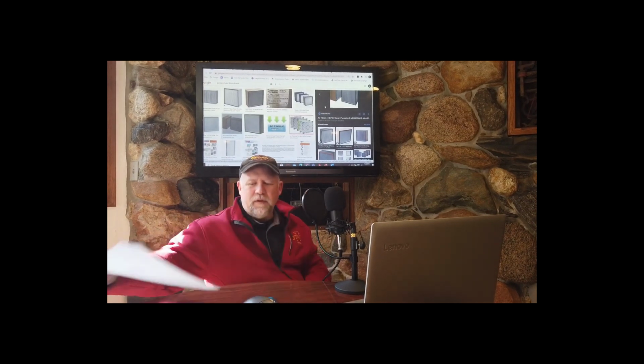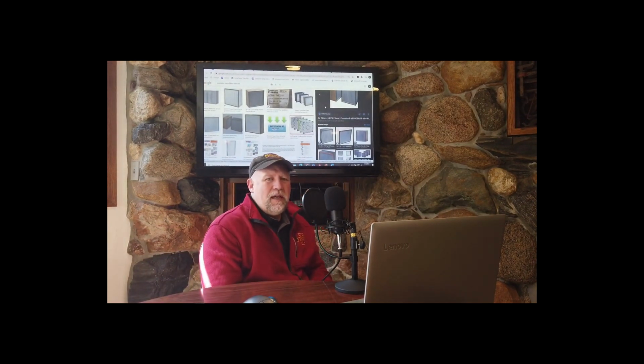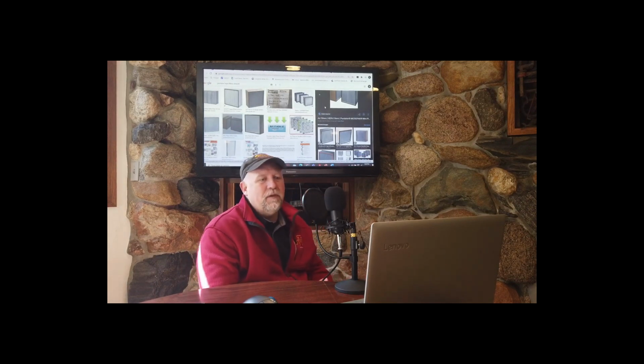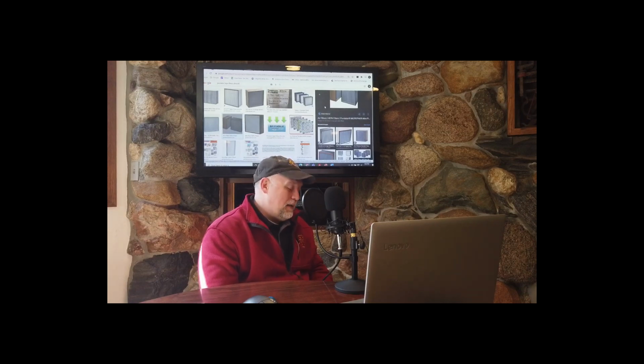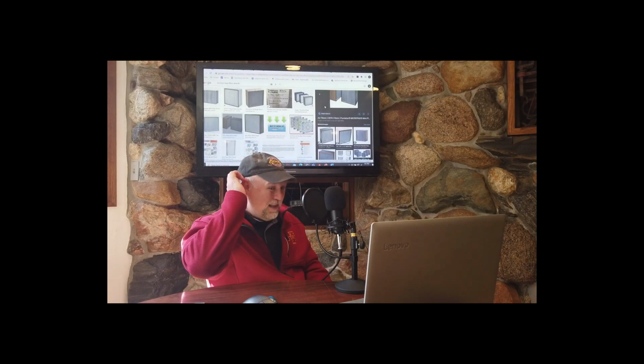Where would I need a HEPA filter? All right, I might need a HEPA filter if I was in a hospital. If you're doing, say, open heart surgery, and this is a life and death type of thing, the air that goes into that room and goes right on the patient, HEPA filters. If you have a tuberculosis isolation unit in a hospital, HEPA filters on the outlet. Captures everything. In recent times, obviously we've learned how important germ control is. You might need HEPA filters for isolation rooms for highly contagious diseases, highly contagious and potentially deadly.